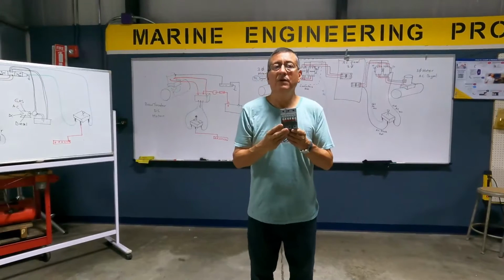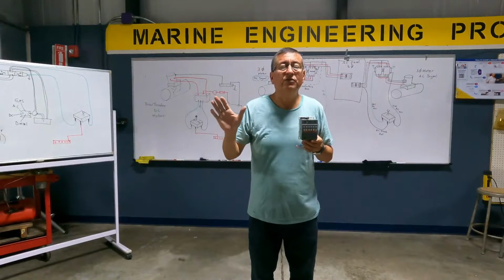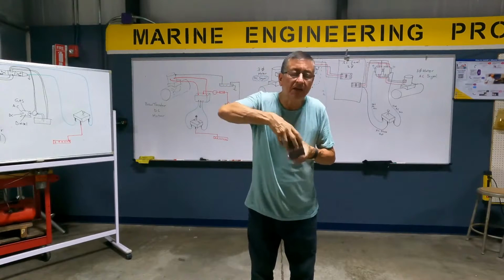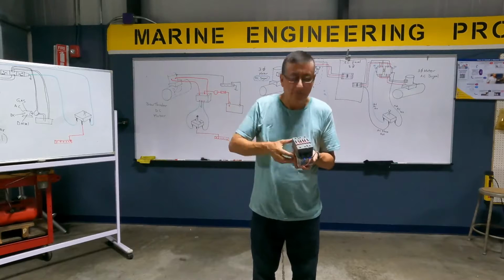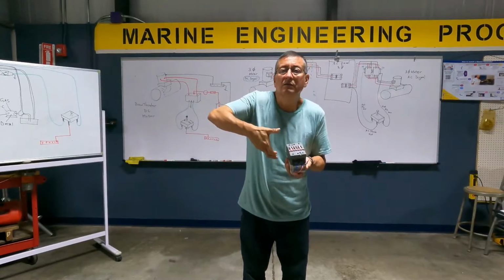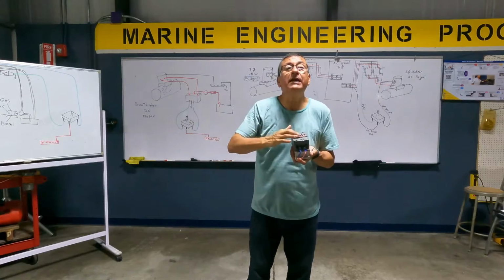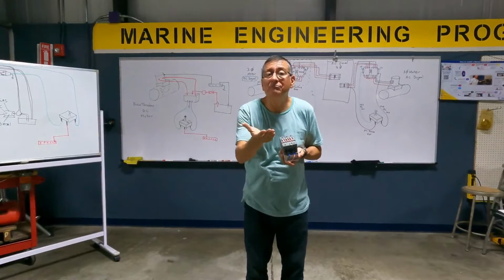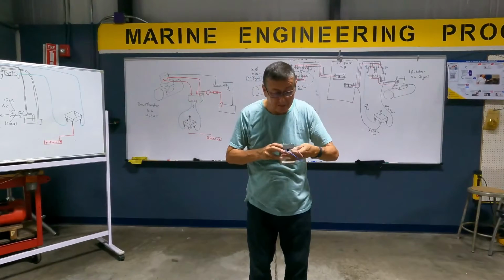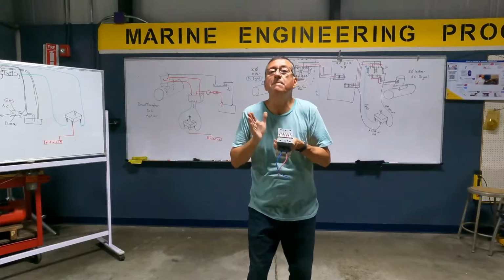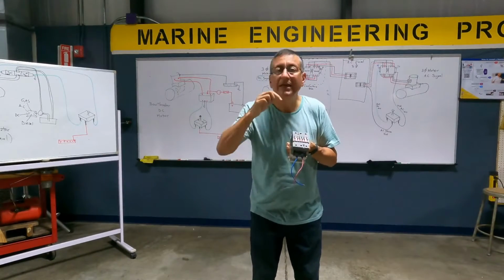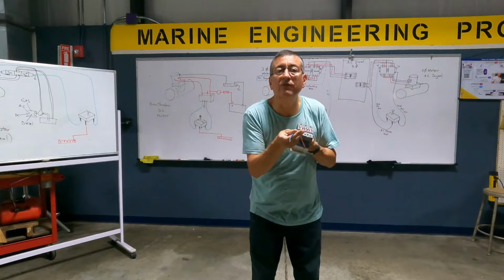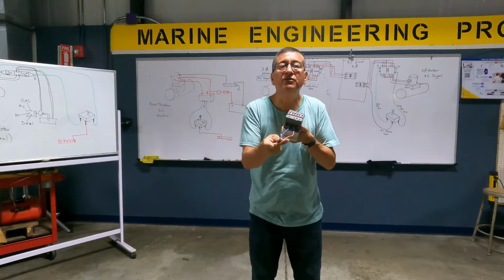You see? The contactor is a typical breaker, 3 phases entering and 3 phases going out. That's the typical breaker. But this breaker can be activated remotely, similar to a relay. In this particular case, this contactor is activated remotely with an AC signal, 120 volts, 110 volts AC, 50 hertz, 60 hertz.